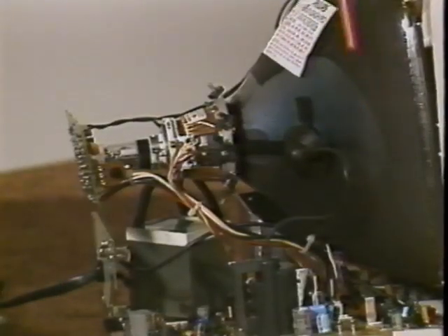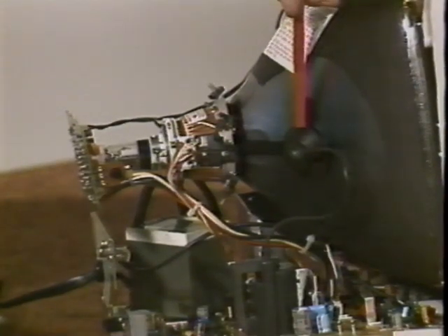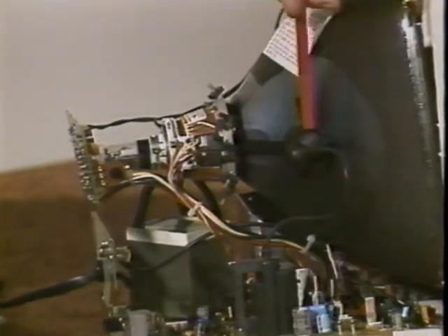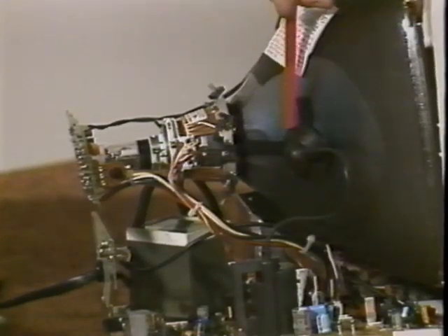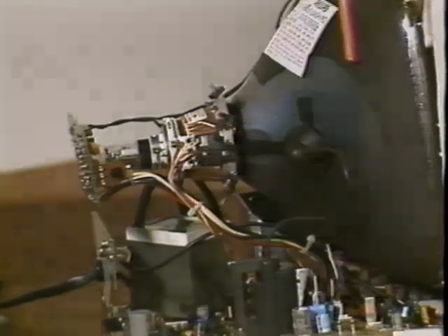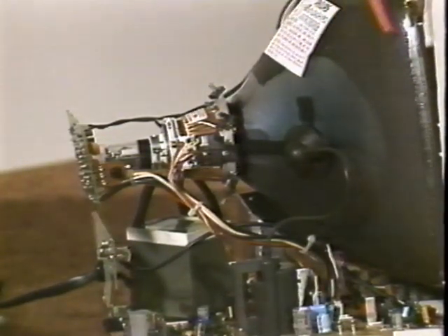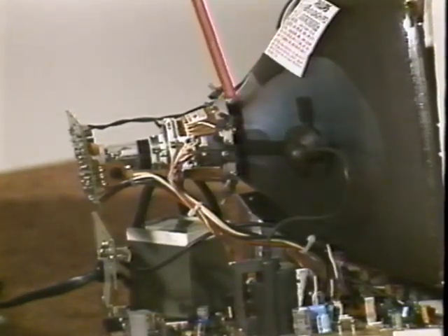The bell of the tube is the large curved area behind the face and tension band. The depression in the side of the bell is called the high voltage anode and provides connection to a coating inside of the bell called the aquadag. The outside of the bell area is covered with a conductive coating called the dag. The dag and the aquadag form a huge capacitor which provides a steady supply of between 11 and 30,000 volts to attract electrons to the CRT's faceplate.